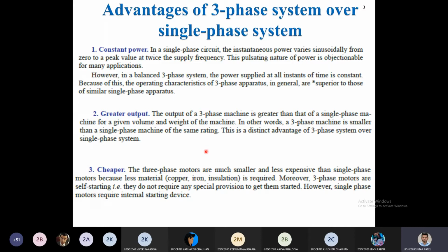So that device, that fan, is inductive in nature. In that, your voltage and current are 90 degrees apart, and that's why it cannot start itself. So what you have to do is start it by providing a capacitor. You balance that inductive load, you lessen that inductive load, and there is a centrifugal switch in some fans, so it will automatically cut out at a later stage.